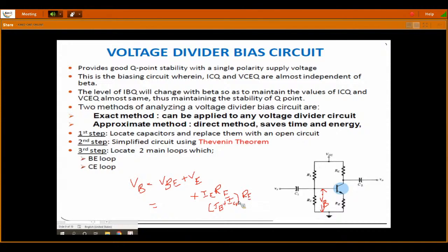Now the advantage is that the voltage divider biasing circuit provides high stability. We would have high stability compared to all the remaining techniques, and this biasing circuit provides quiescent values which are almost independent of the current gain or beta factor, as well as independent of temperature rise, due to the compensative methods which we utilize in the voltage divider biasing technique.